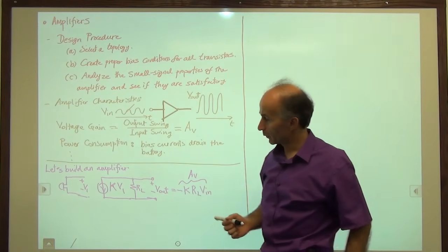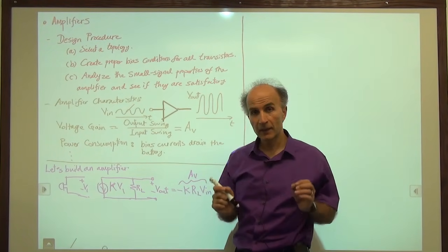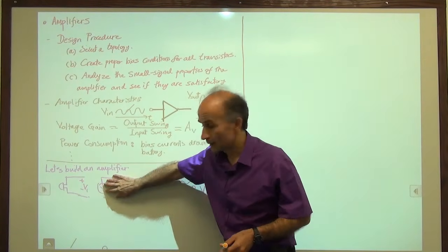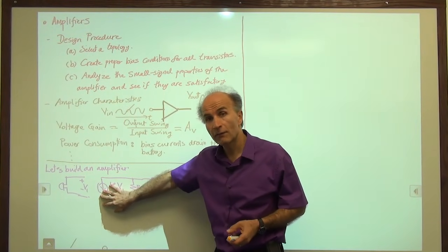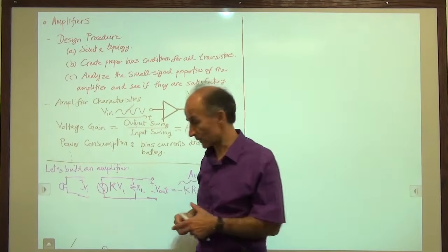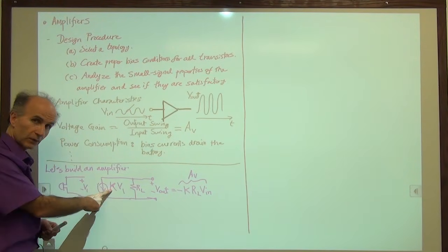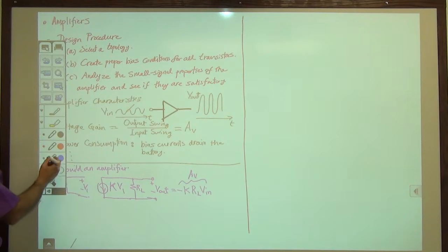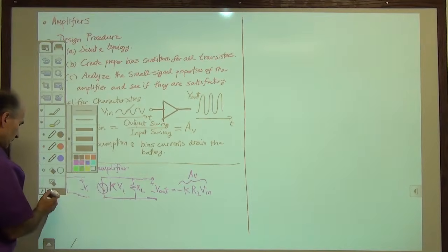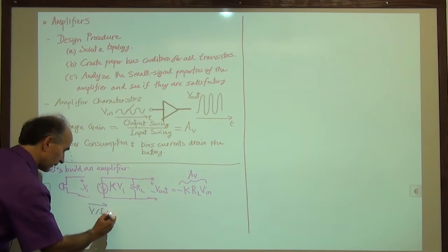All right, then we realized that a bipolar transistor has the same ability. This ability is sometimes articulated as follows. We say this device, this voltage-dependent current source, converts a voltage to a current. Converts. So that's the term that we use. It sees a voltage, generates a current in proportion to that voltage. And in fact, sometimes we use this notation for it, which I hope you will not find confusing. So we say V to I conversion.